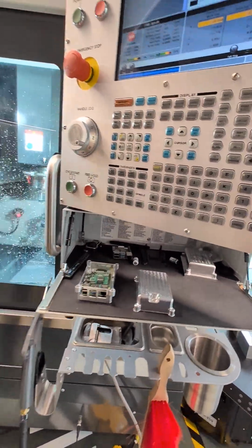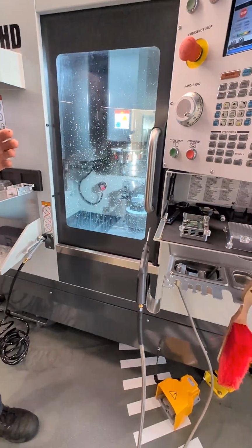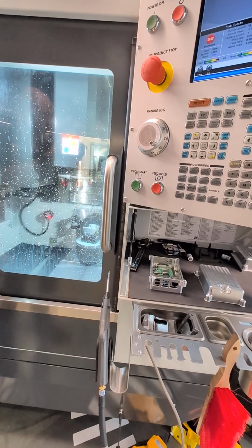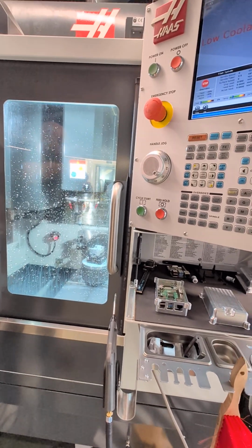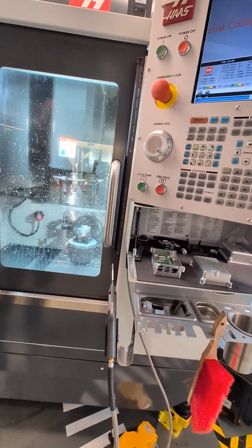So really it's most effective when you've got a cutter or a drill. Best with drills, because they've got holes that go right through to the tip, and you're in a hole. There's no way. It's designed to flush those chips back out. So that's what it's really designed for.